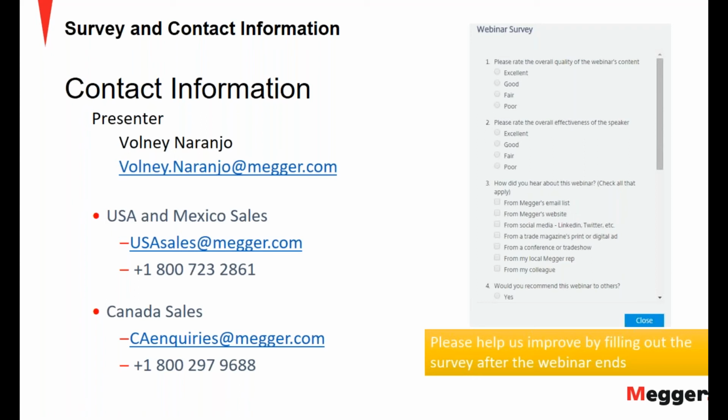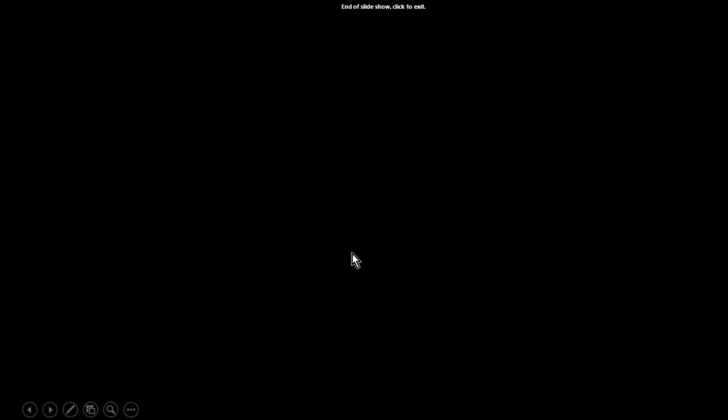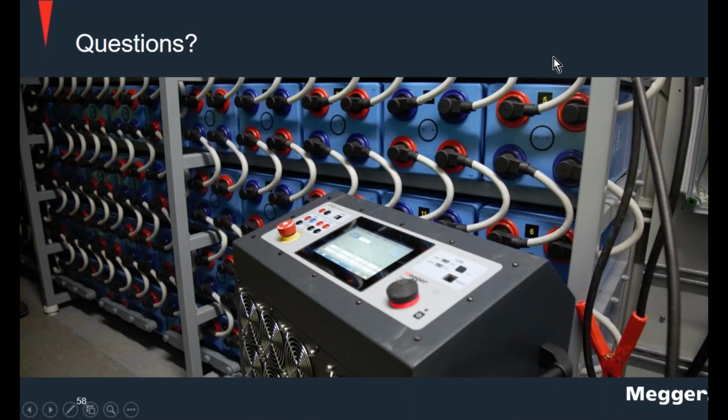However, you do need to take some precautions in doing that, especially if you have parallel strings, because the battery monitoring systems will have cutoffs on them. So if the voltage gets too low, it'll cut off that string. So if you're pulling a load on the entire system, and one of those strings goes too low, it'll cut out. And then the full load will be put on the other strings. And what could happen is you could end up blowing a fuse on them. So you do want to be cautious if you're doing a discharge on a lithium ion parallel string.